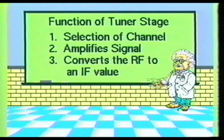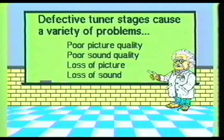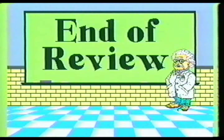The tuner section has three main functions. First, it selects the desired channel. Second, it amplifies the weak RF signal. Third, it converts the RF signal to a much lower intermediate frequency value. Defects in the tuner stage can cause problems in the image, color, and sound reproduction within the television receiver. This concludes review number 1.